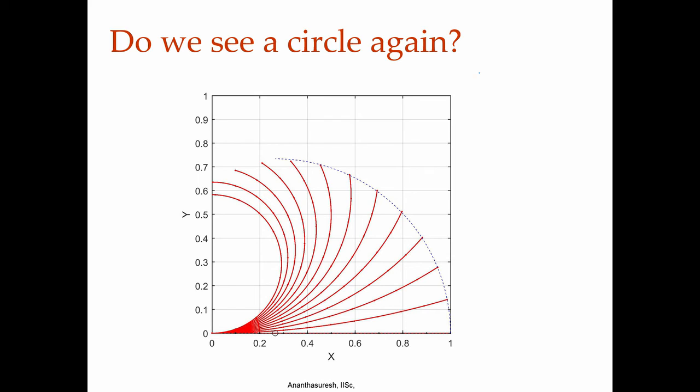Okay. Now, if you see there is again a circle, right. If we draw this dashed line here, that approximates the locus of the tip quite well. Here it is almost wrapping around, right. So, for that kind of a deformation, which is practically good enough for most compliant mechanisms, there is a pure moment load, again there is a circle.